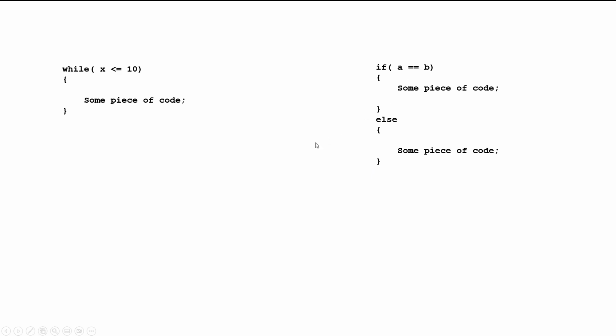For checking conditions, we can actually use our ALU. For example, if we subtract a number from another and the result is 0, it means that both numbers are equal. If it's positive, then A was greater than B, and if it's negative, A is less than B. So we can add a few more opcodes for branch not equal to 0, branch equal to 0, and branch positive to support different kinds of checks.